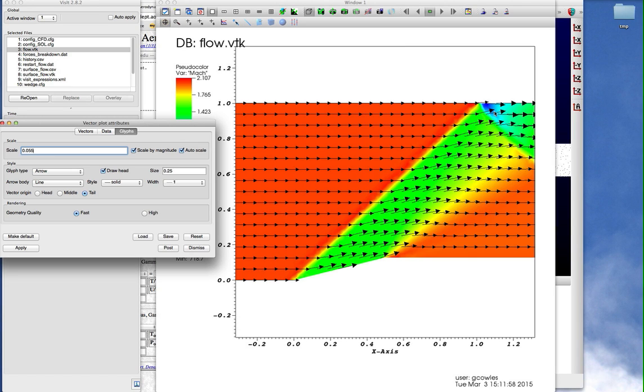So something has to turn it back. So you would have another oblique shock wave right here, a reflected shock wave, which would turn the flow back to being parallel. So it turns up 15 degrees, now it's going to turn back 15 degrees. So it should be passing through another oblique shock.